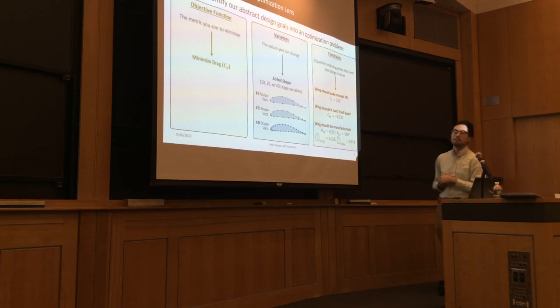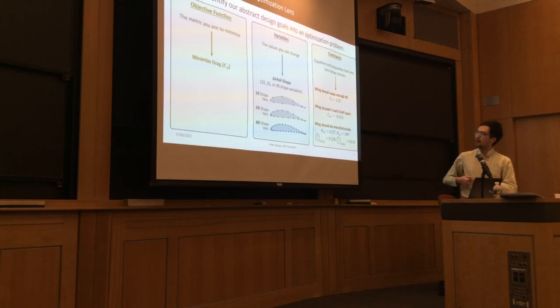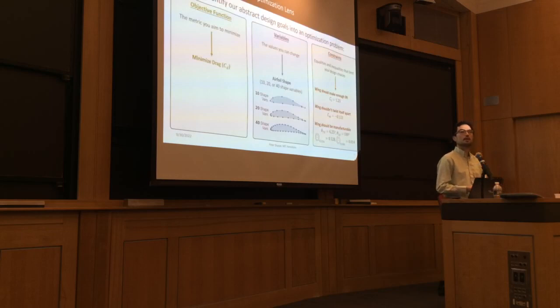And then to your other question about the method itself, so anytime you're looking at high dimensional optimization, which 20 maybe not quite high dimensional, but if you look at a whole airplane, that's very high dimensional, you want to use gradient-based optimization, just because the gradient-free stuff doesn't scale very well with respect to the number of input variables that you're optimizing over. So what we do here is it's a stabilized Newton approach with a line search in the middle, kind of a standard off-the-shelf method with an exact Hessian because it's not very many degrees of freedom.